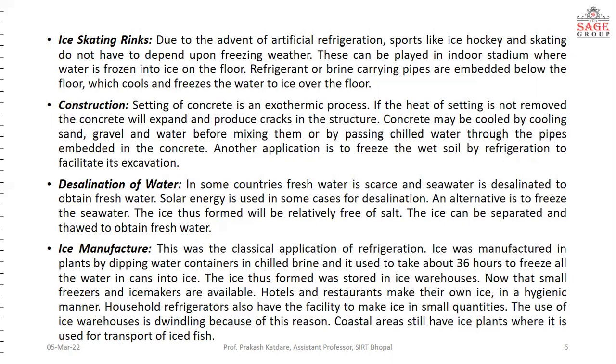Construction. The setting of concrete is an exothermic process. If the heat of setting is not removed, the concrete will expand and produce cracking in the structure. The concrete may be cooled by cooling sand, gravel, and water before mixing them, or by passing chilled water through the pipe embedded in concrete. Another application is to freeze the wet soil by refrigeration to facilitate its excavation.